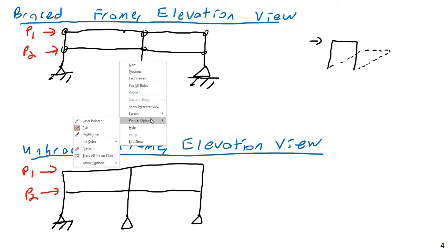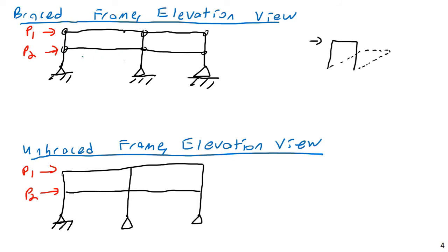So how do we deal with this in a braced frame? Well, it's in the name. We add braces. Braces are just some sort of diagonal element that we add to a frame to reinforce it or to carry the lateral loads. So you still don't have any fixed connections. You can do all of this with pin connections. But by adding diagonal braces, in order for this frame to flop over like this, it's going to actually have to put one of these members into tension or compression.